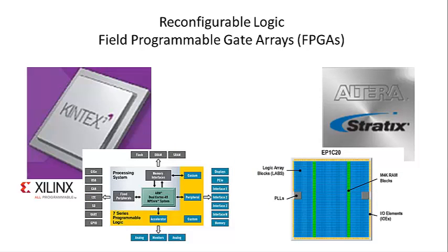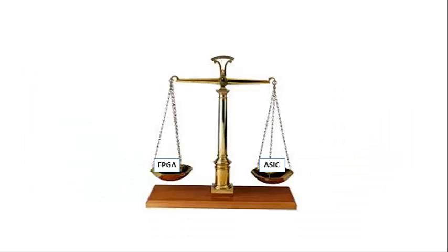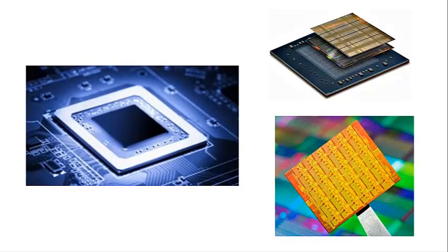It uses reconfigurable logic integrated circuit devices, also referred to as FPGAs, field programmable gate arrays. The techniques learnt using viciLogic can be used to design either reconfigurable logic hardware, FPGAs, or full custom integrated circuits, termed ASICs. Integrated circuit devices contain vast amounts of hardware resources, from thousands to millions of digital logic building blocks and memory elements. Digital systems design engineers and computer architects connect these logic resources together to create sophisticated, high-performance hardware.